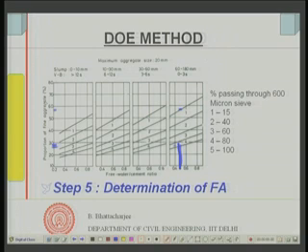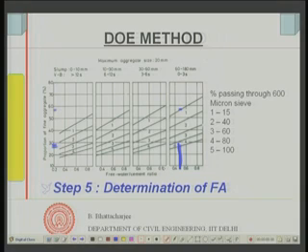So, I needed much more fines, because of the mobility of the aggregate, I need more paste, more mortar even. So, the more mortar is ensured by this. So, in case of coarse aggregate, more fines would pack into the voids of the coarse aggregate system, larger size they are. Even when I have this 15%, it means 85% is passing through this.